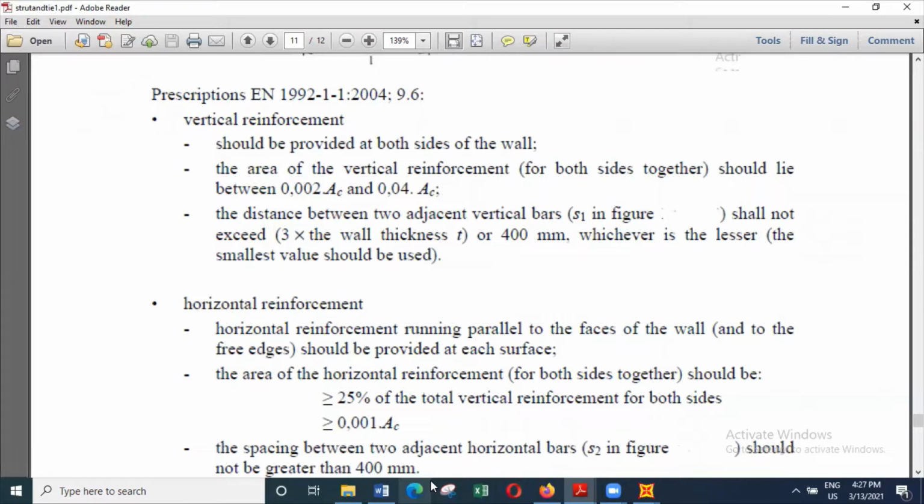To analyze that, you will need a strut and tie model, because now the wall is subject to concentrated loads. All the loads that come from above should be transferred onto the supports. Because of that reason, you'll get concentration of loads and also changing of load paths.